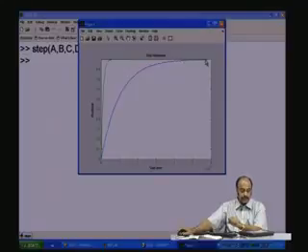And another important thing is this is a first order system, and therefore, there are no overshoots. There could be overshoots if you have LCs, the resonance effects, then you will see that this can overshoot like that and then damp out. So, these are some of the things that you will be looking for and trying to tune when you are doing your time domain analysis.